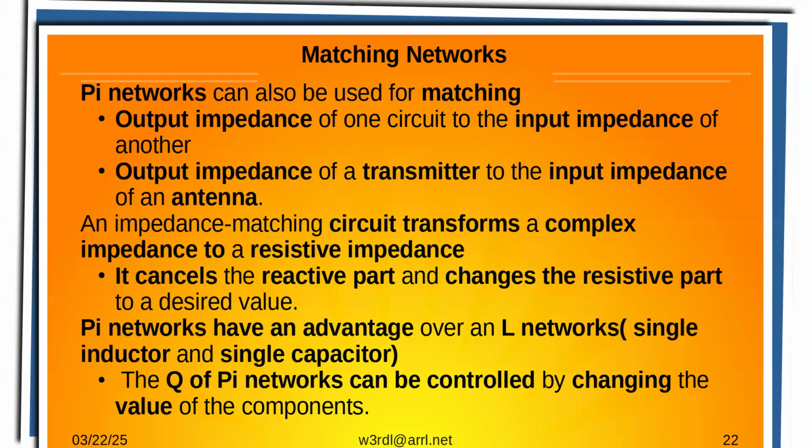So 75 ohms is going to be on 1.5 on the scale, or 50 would be 1. So you want to find that point and what the opposite reactance would be to cancel out and give you 0 reactance at 75 ohms.